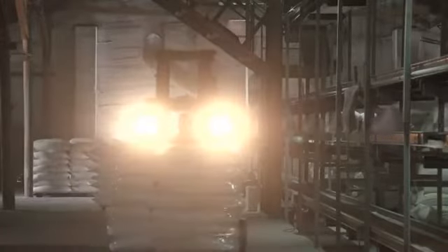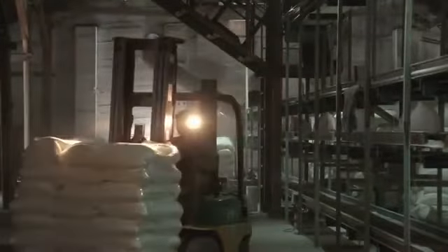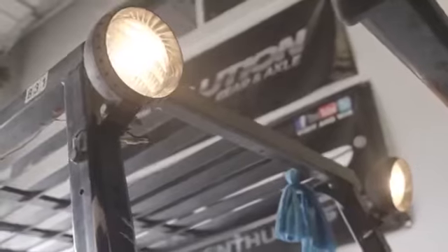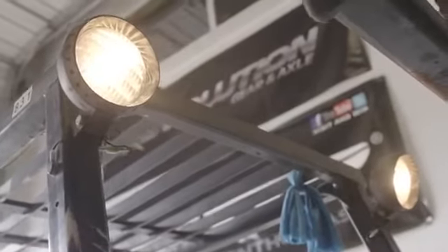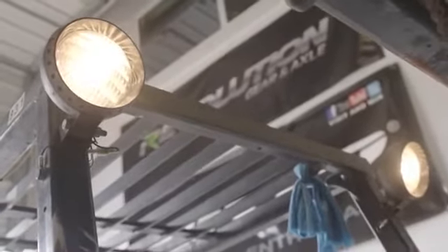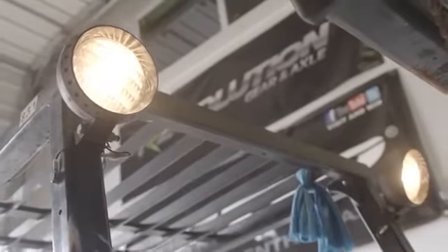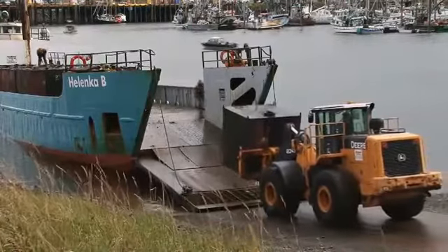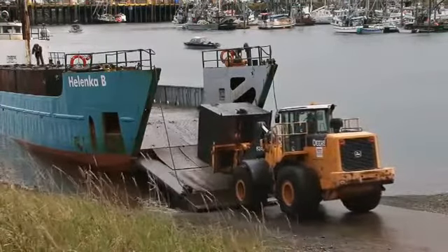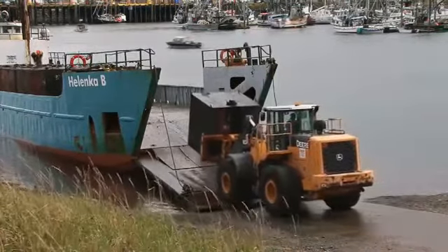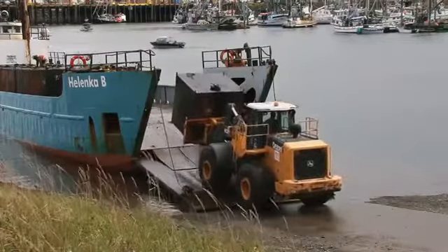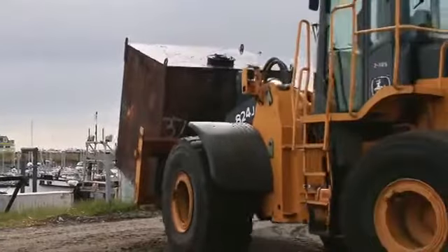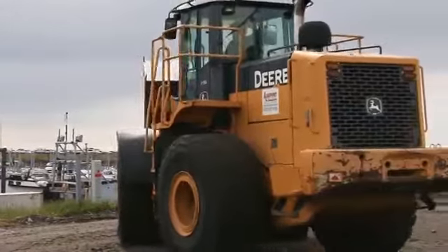Equip forklifts with headlights where general lighting is less than 2 lumens per square foot. In general, if working at night, outdoors, or in any area where additional lighting would improve visibility, the forklift should be equipped with headlights. Ascend and descend grades slowly. When a grade is in excess of 10%, loaded trucks must be driven with the load up grade. Reduce speed when turning and never turn on a grade.